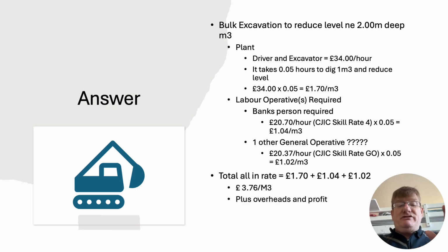But I might also need another operative there because this time I'm digging more. I might need some more help. And if I wanted to, I could add on a dumper as well with a driver. So a dumper with a driver would be another operative as well, and I'd need a price per hour for the dumper. But you could say, look, dumper and driver, I'm going to put in the preliminaries. So this is just for this particular unit rate.